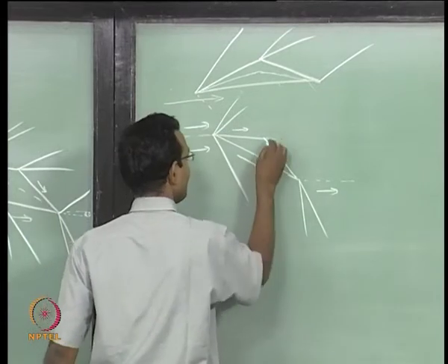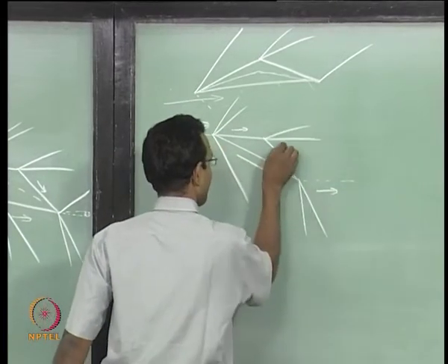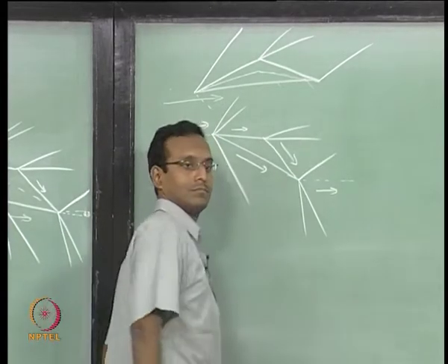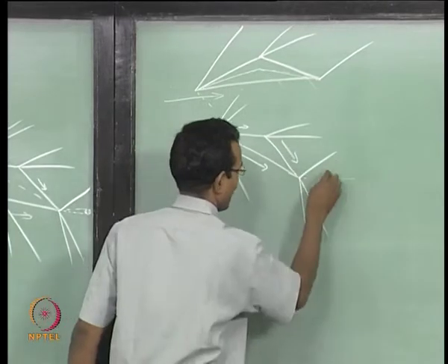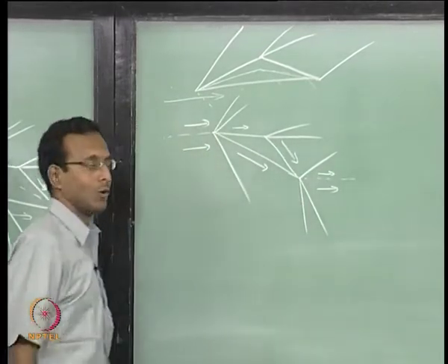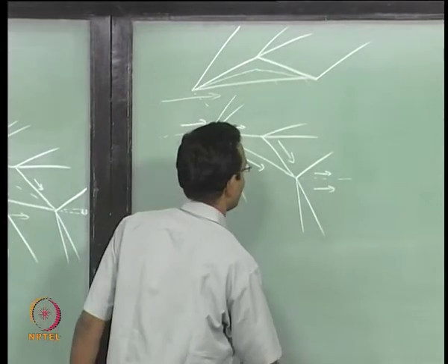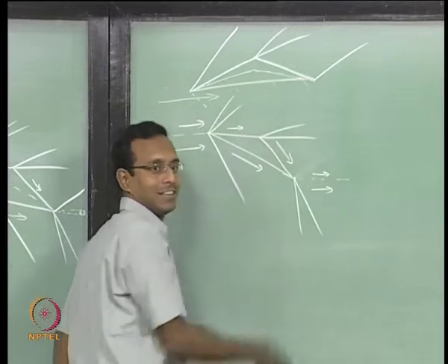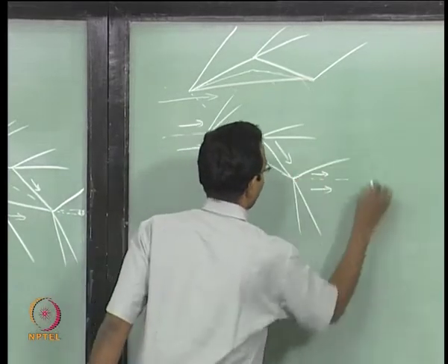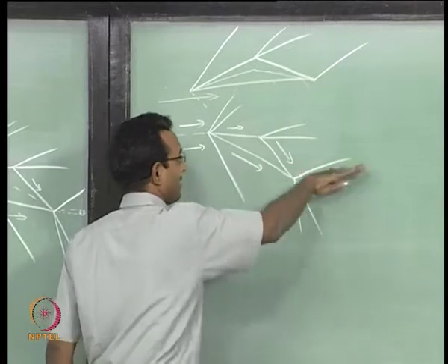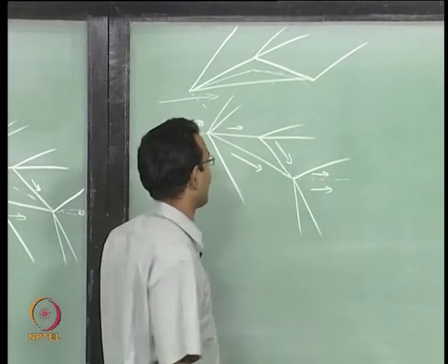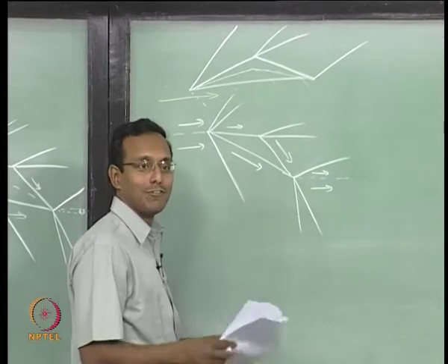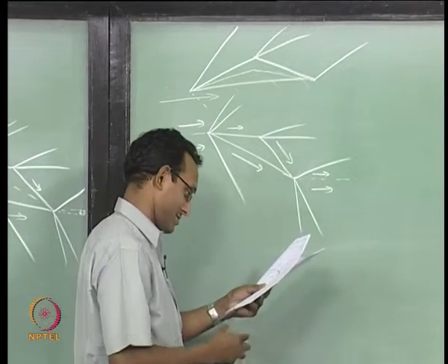Flow goes like this, another expansion here, flow goes like this, finally there should be a shock, because the flow has to come here, turn and go this way again. A whole set of things happening here. I have drawn it such that this shock angle is 90 degrees, that is very, very wrong. 90 degrees with respect to streamline will never happen. I am assuming attached shock still, so it is going to be less than 90 degrees with respect to incoming. Okay. So this is more like a flow field. You should be comfortable in drawing such flow fields around different bodies, that is the idea.